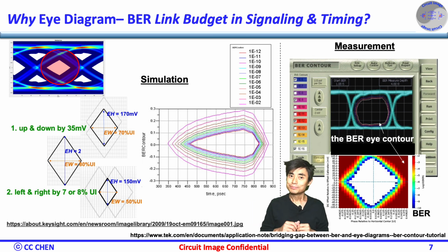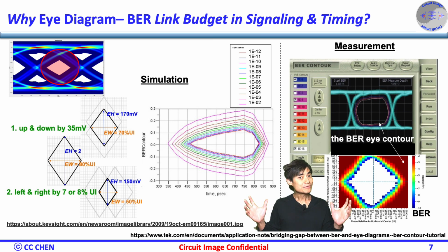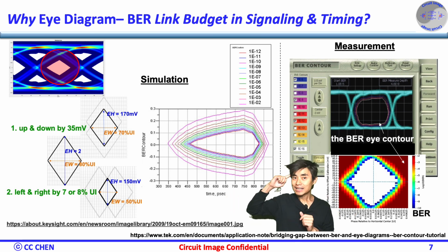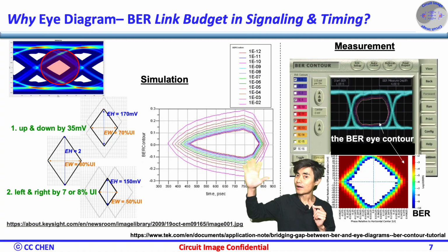The interaction between the eye width and eye height shows the resulting 2D eye is precise enough compared to the bit error rate eye contour from the system simulation or silicon validation. To make sure we could meet the target bit error rate, should we specify what the eye should be? Think about the eye mask image for 5 seconds.